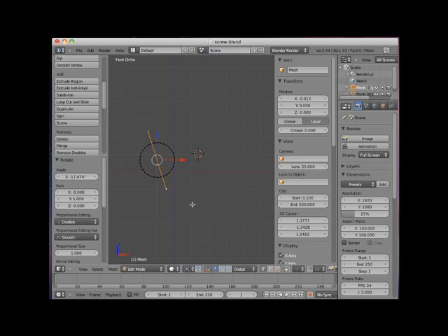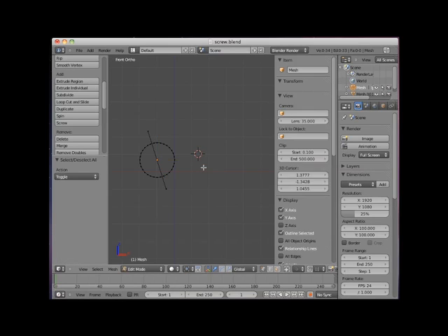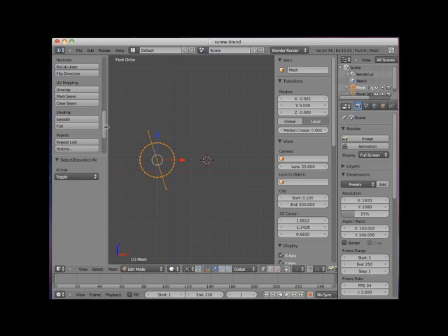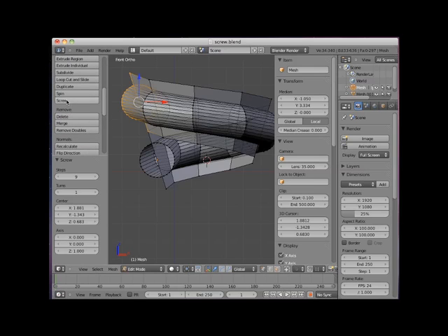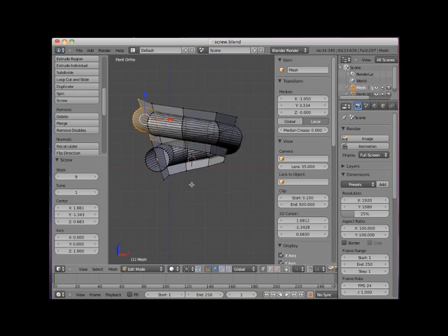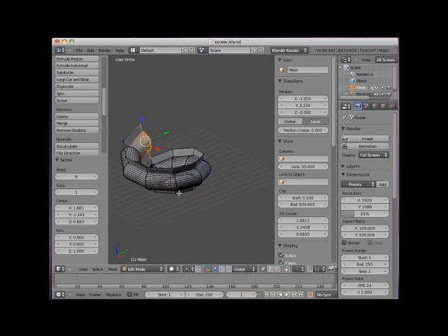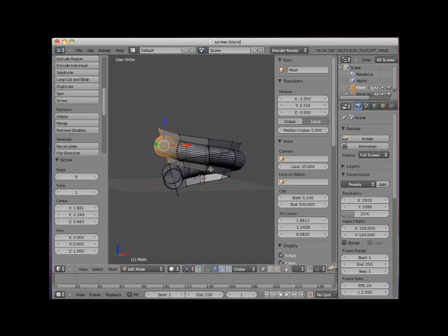I'll then select all of the vertices and place my 3D cursor to the right of the selection. I'll then press the screw button in the 3D Editor Viewport Tools panel. The screw operation again extrudes the selection one turn, producing 9 segments. It also translates the selection along the Z-axis by the difference in the Z location of the polyline end vertices. But here it also translates the selection along the X-axis by the difference in the X location of the polyline vertices. I'll increase the turns to 6.